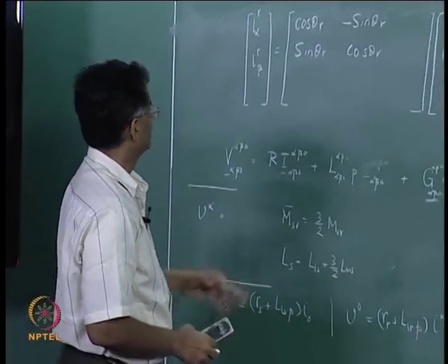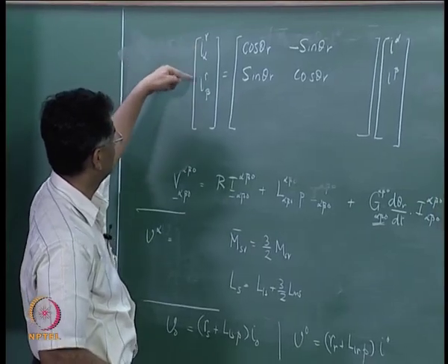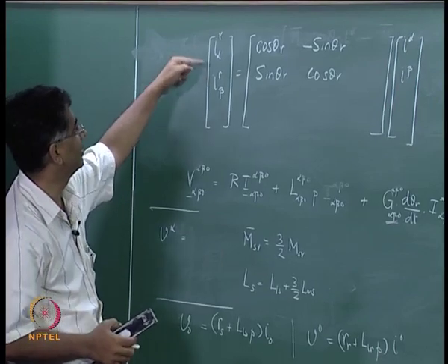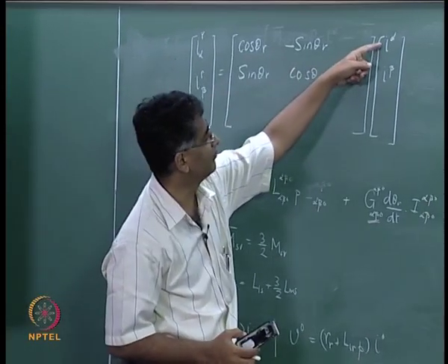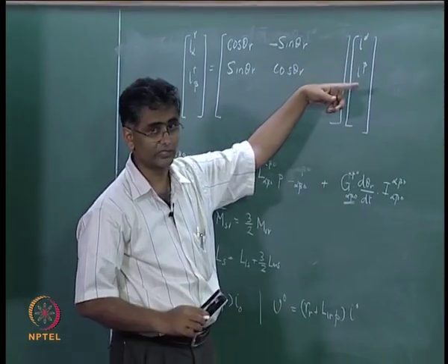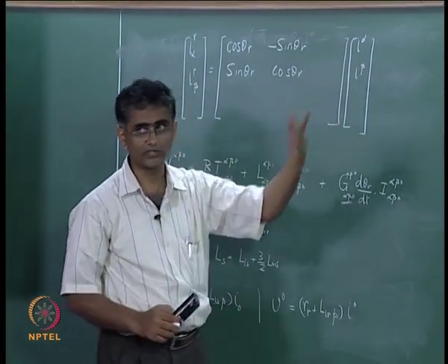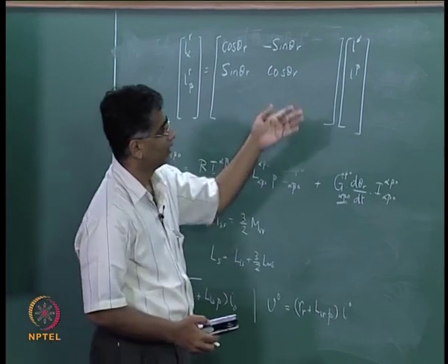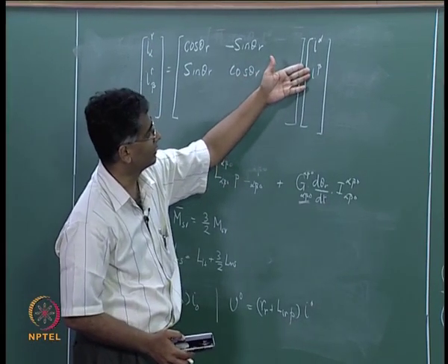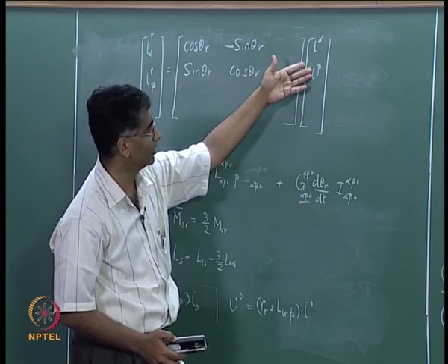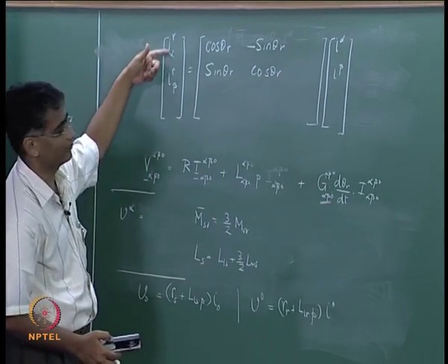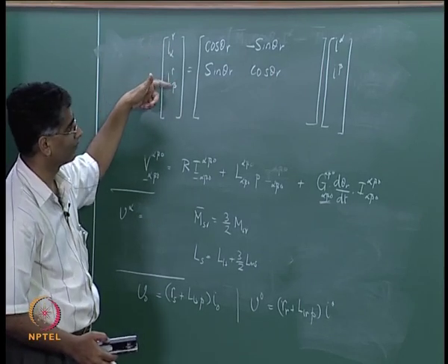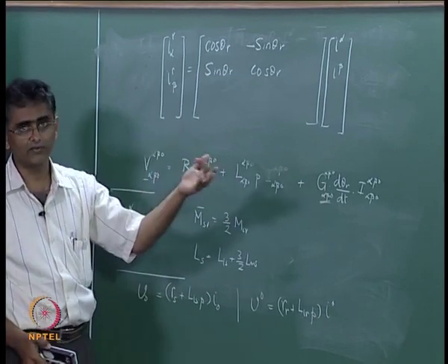If we do this, then we find that these currents are really flowing in stationary coils, albeit pseudo stationary coils, and these are fictitious currents. These are flow of currents in the two phase machine, which we have arrived at from the three phase machine. In this manner one can now transform the flow of currents in a rotating reference frame, that is the alpha beta reference frame, into a pseudo stationary reference frame, which is alpha beta again, but these are fixed to the stator. This is only with respect to alpha and beta.